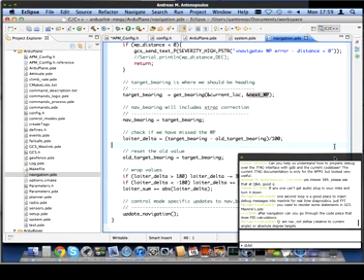And there's a lovely little demonstration, the Flash demonstration in the ArduPlane wiki that was done by Jason Short, that demonstrates how cross-track correction is done. So anyway, we work out what the target bearing is, and then we call update navigation, which then updates the nav roll and the nav pitch.